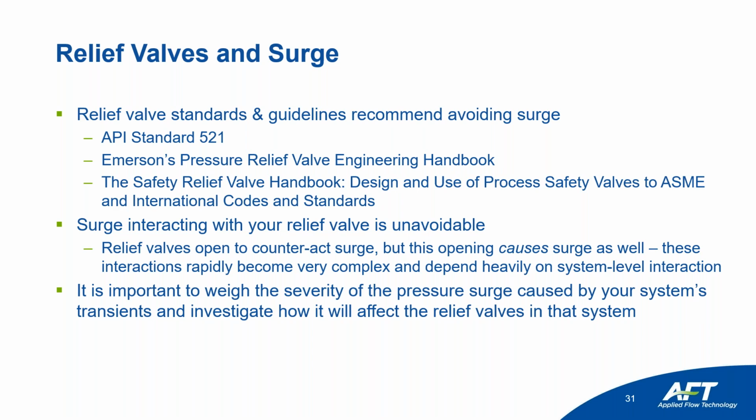And that opening causes a downsurge, which causes more problems. And these interactions can rapidly get out of hand because you have a very large, complicated, complex system. And it really relies a lot on system level interactions with the relief valve. So in reality, it's important to weigh the severity of what is causing a pressure surge or these anticipated pressure surges in your system. And you need to consider how it will react with these sort of unintentional transient devices like relief valves and check valves.